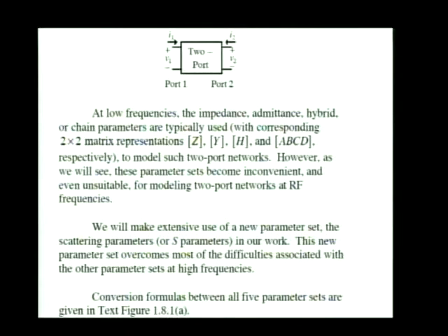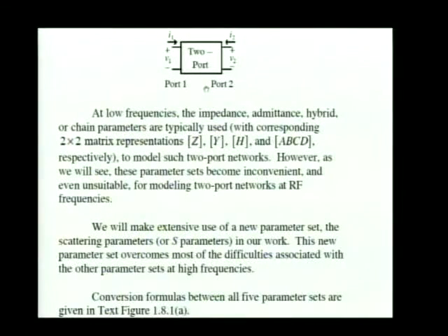So this is a great thing for programming into a computer. You can do it by hand if you have to. That is to say, if you're given the Z parameters of the 2-port and you want to do some high frequency analysis, you need the S parameters, you can do a conversion from Z parameters to S parameters. Definite formulas there will do that for you. And the opposite, you can convert from scattering parameters back to the low frequency Z parameters.